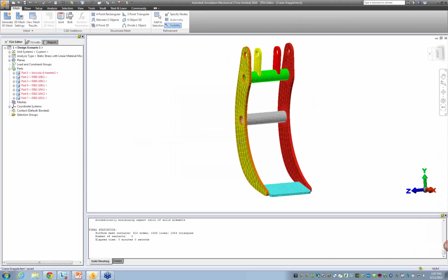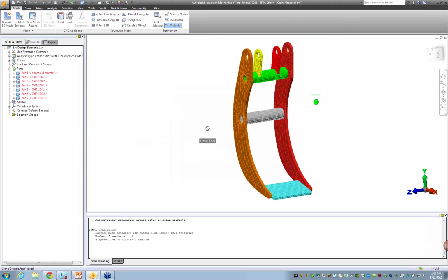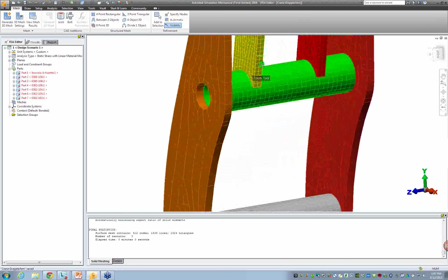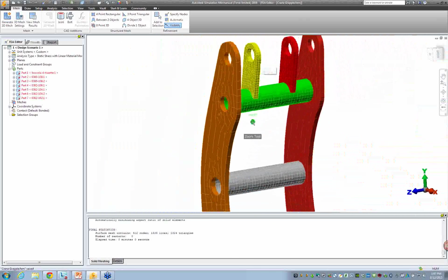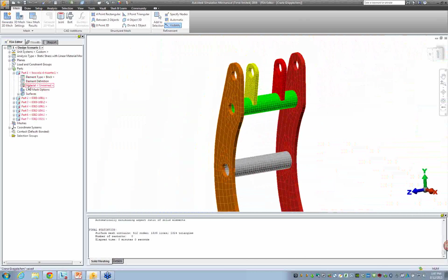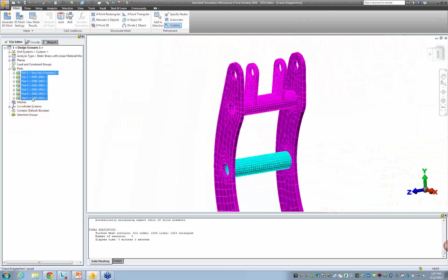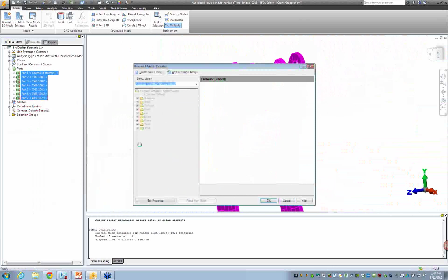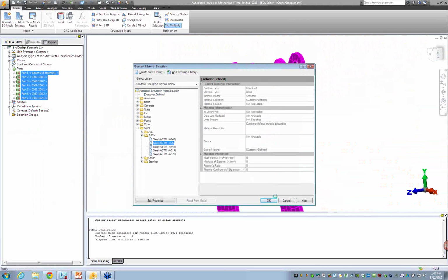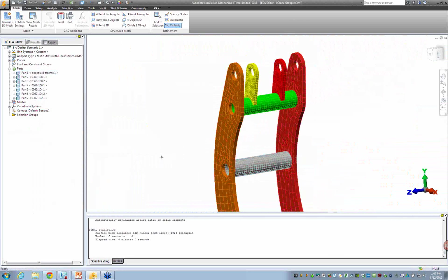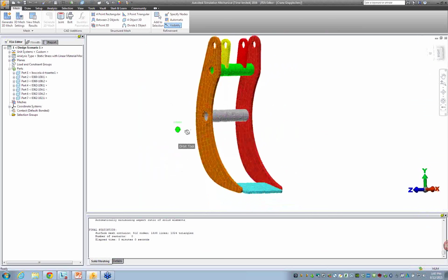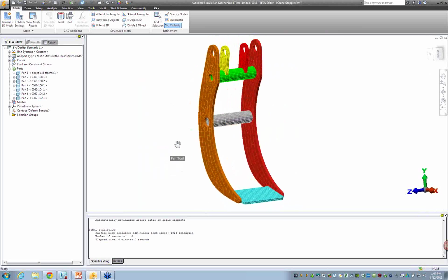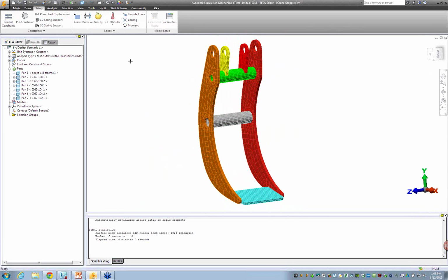And in an ideal world, I could just simply take this very first mesh and start adding loads and boundary conditions and start analyzing my model. But then let's go ahead and add some material so that these red icons go away. So I'll go ahead and add a default material of steel. Like I said, if everything worked the first time, or if I was happy with the mesh results and how the mesh looked, I could be setting up my analysis with some loads and boundary conditions and run the analysis.